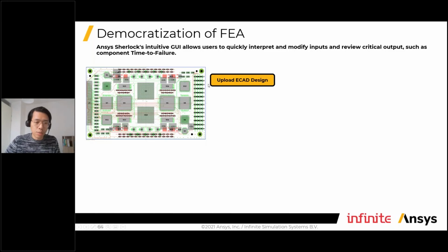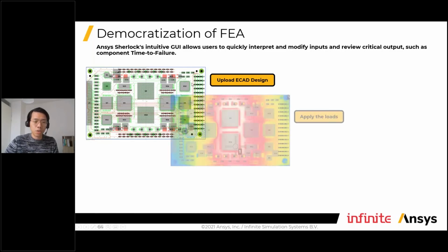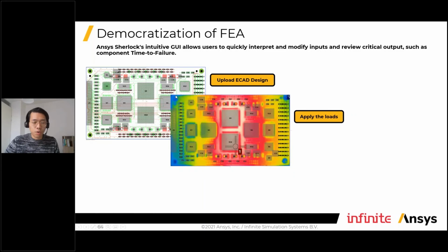So this is actually the beginning, where you bring in your CAD. Once you bring in your EDA layout, it immediately gets recognized by Sherlock, and then you can already see that all of the components, layout, and traces are imported. And of course, you probably will spend some time making sure that the components are indeed the correct components.